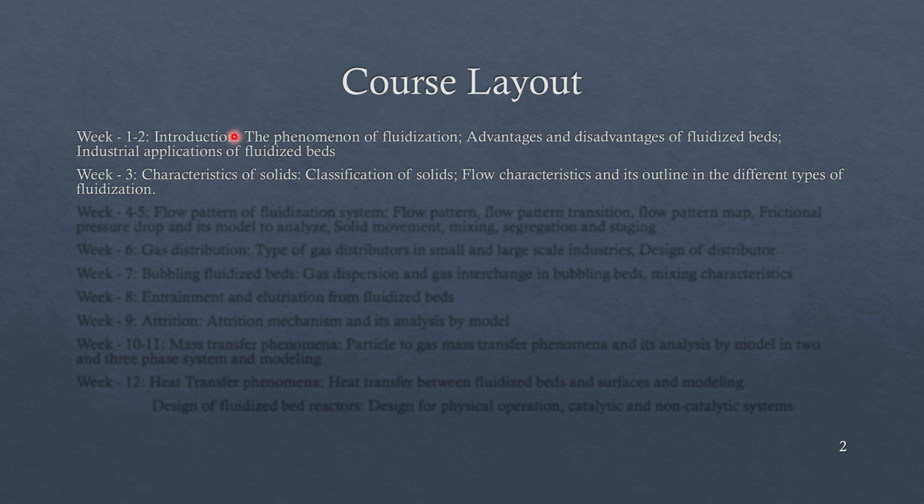With a much larger increase in size, we come under Geldart B particles. These Geldart B particles are also widely used, and they are prone to bubbling. That is to be noted when we are dealing with Geldart B particles. But the last category, the very largest of particles, comes under the Geldart D particles. These Geldart D particles are very difficult to fluidize, and they lead to spouting, so they are used in spouted beds, because they are not easily used in normal fluidization.